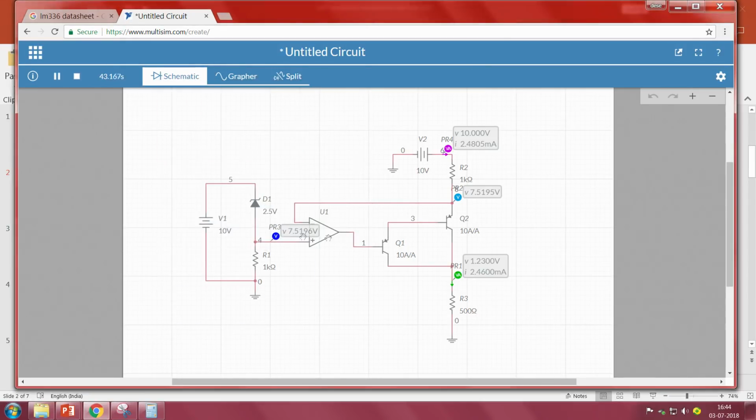So, by using an operational amplifier, we can provide a constant current to our resistor, and by finding the voltage drop across the resistance, since that is a constant current, it is easy to identify the unknown resistance, right. So, we will see whether it is working in the same way in our circuit too, in the experimental model.